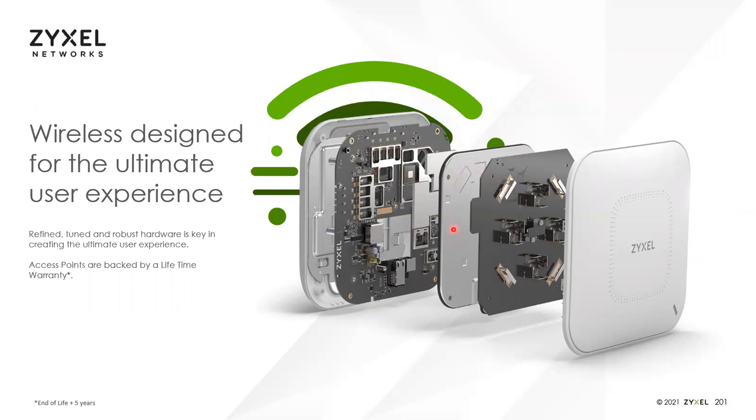You will notice we then have another metal plate generally above the PCBA. So this acts again to help draw heat off the board. It also acts as an RF deflector. And then you will see our antennas are mounted onto their own PCBA or their own little mounting bracket inside, off the board. Most of our competitors, even the really, really expensive ones, are putting their antennas directly on the PCBA. By creating separation between the antennas and the PCBA, it helps with signal to noise ratio. It can make a big difference on those edge case connections.